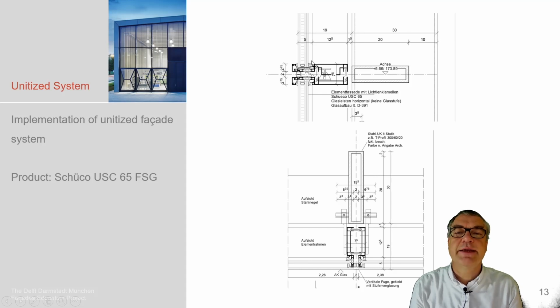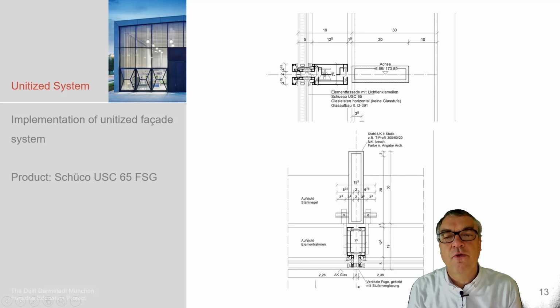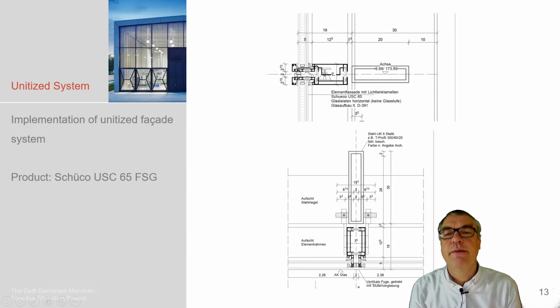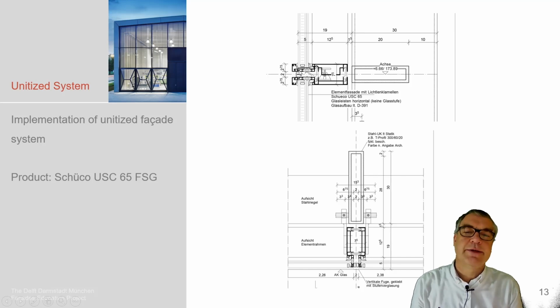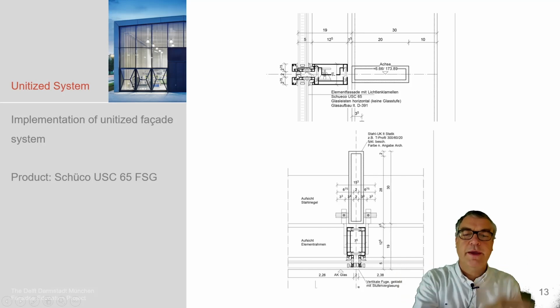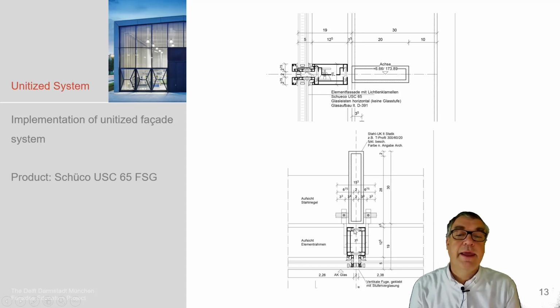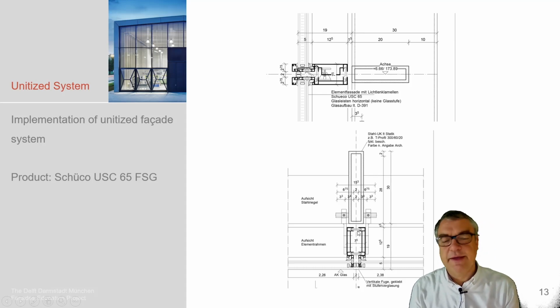The sealant of the glass inside and outside happens here, and then these two profiles being connected, they have to be sealed at the inside, again airtight, at the outside again rain proof, and having an additional layer of rain-proofment as a second outer layer. So we have two outer layers and we have one inner layer. And we see the same in the horizontal section, the first outer layer, the second outer layer, and then the inner layer to guarantee that the whole thing is airtight as a total system.